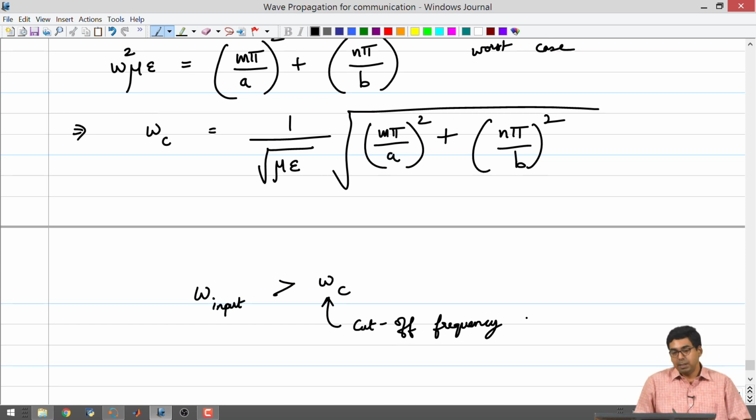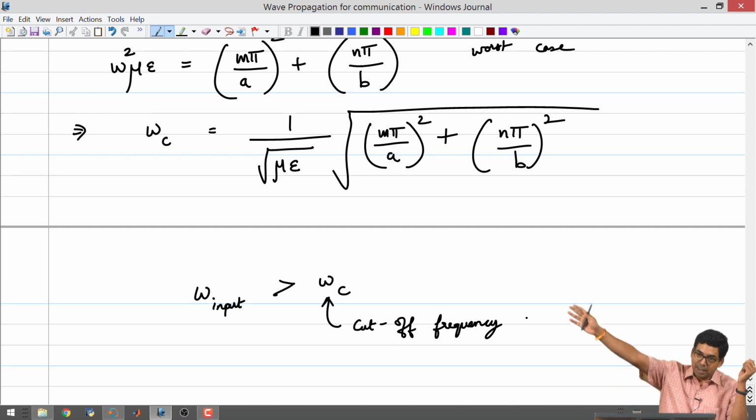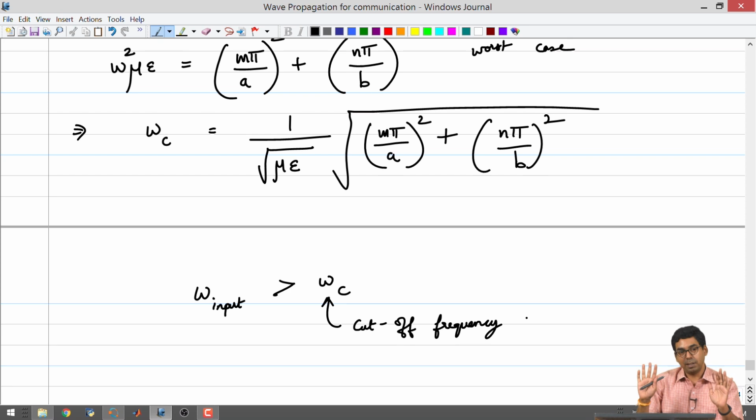These two cases are very similar, parallel plate and rectangular, just that the parallel plate was very easy to analyze because it had only two interfaces, but now you have many interfaces coming into the picture. So, we used a different approach. We started with the general solution and then tried to see, based on the standing wave patterns and the travel direction, what kind of approximations you can make and come up with a solution that actually seems to be valid: traveling wave in the z direction, standing wave pattern in the cross section.